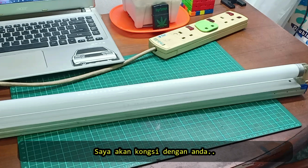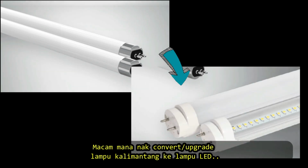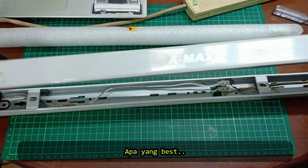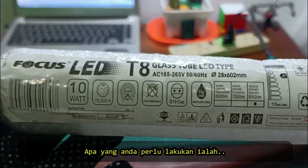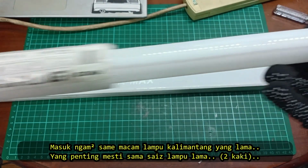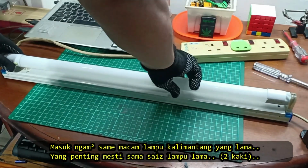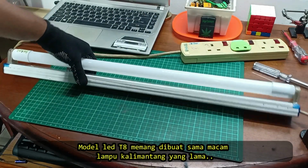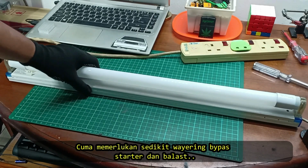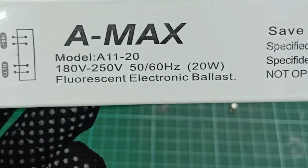In this video, I will share with you guys how to convert fluorescent lights to LED. The best part is, you can reuse the old lamp casing. All you have to do is buy an LED bulb, and it will readily fit into the same screw-in sockets used by incandescent and CFL compact fluorescent bulbs. These products are designed to be installed directly into an existing fixture. This requires that the fixture be rewired to bypass the ballast, which can either be left in place or removed.